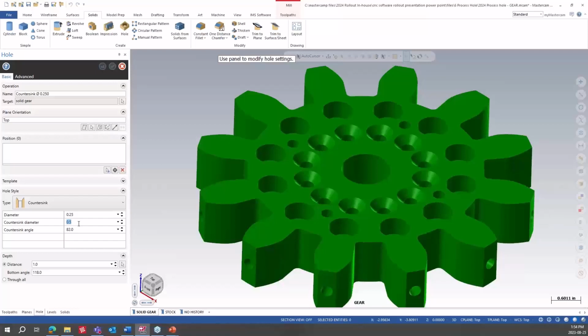You want to design and draw as your part needs to be machined, essentially. Exactly. That's why I was saying, if you're designing in-house and building in-house, like a tool and die shop, you could design those holes. Because right now, if you pick that 1/4 inch hole, it's going to apply many different processes, and you have to select. If you were to design that solid, and from the design itself it comes out as 234, then you know that that's a tap drill size.